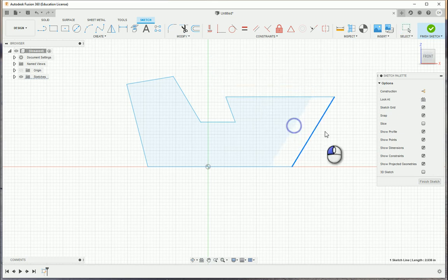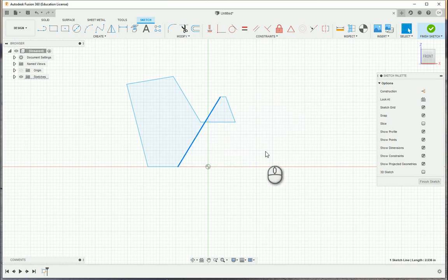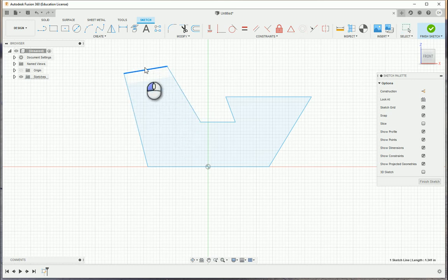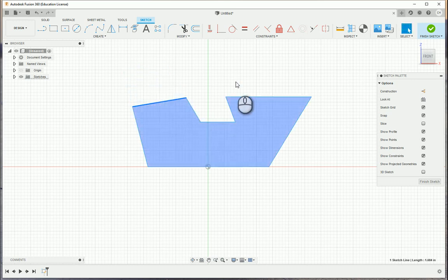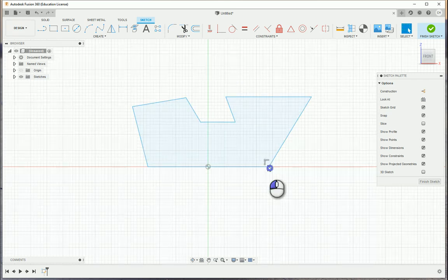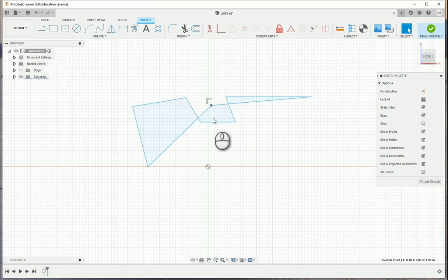This is the thing that students sometimes get a little frustrated with: when they go to dimension something, a sketch will move on them and then their shape becomes something like this. Well, all you need to do in a lot of cases is drag that blue line and get the original shape back. Sometimes they get a little worried that they've messed something up, but just by clicking and dragging on those, you can see how it works, even on these coincident points.